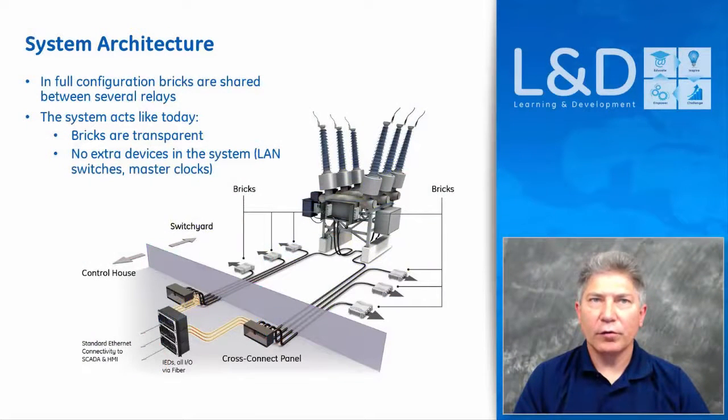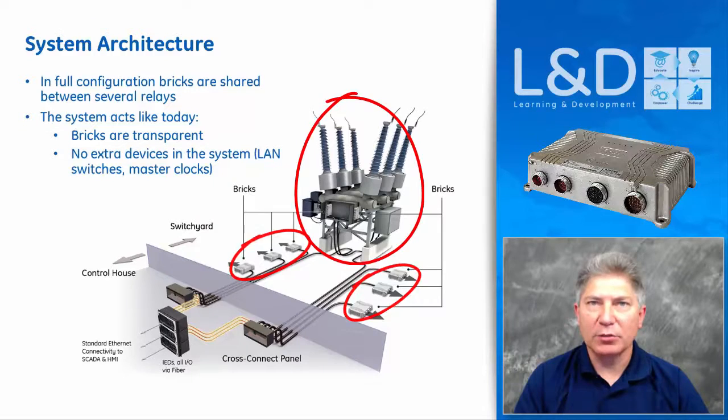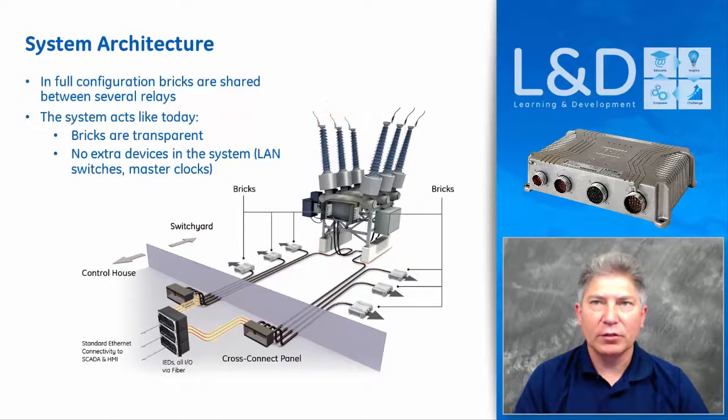Here is an overview of a system utilizing the HardFiber configuration. The primary role of bricks is to limit the amount of copper wiring by containing it as close to the power apparatus as possible and to provide a transparent and unified digital interface to the relays.